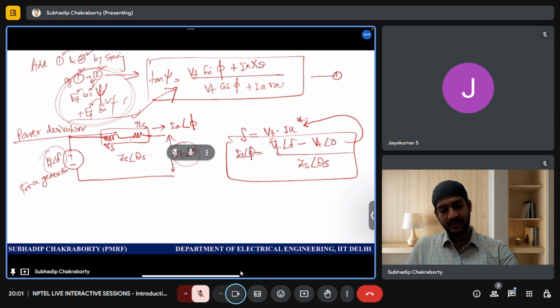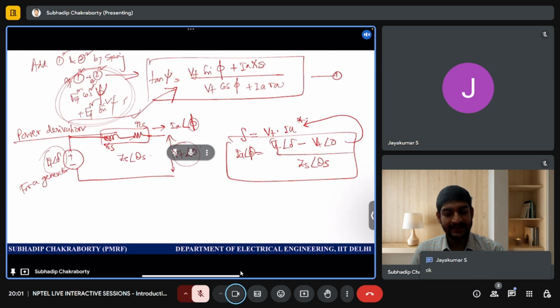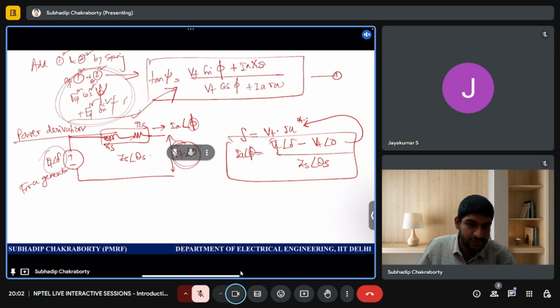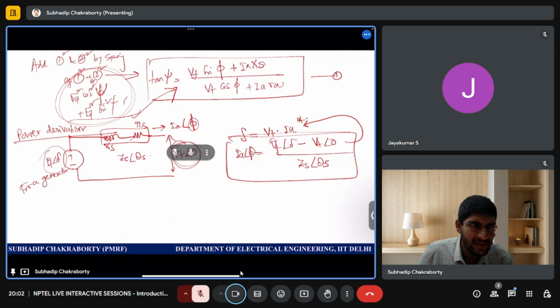This is phi, yes, because of the power factor angle, this one. The angle between VT and IA, and I took the reference of VT, right? That's why I'm telling phi. So VT has an angle 0, and with reference to VT, IA is standing at an angle of phi. So I should write phi. I need to take one reference and write all angles in reference to that angle. So as we can see, the angle between VT and IA is phi. That's why I'm writing phi. Now plus phi or minus phi, the formula will give me. I know that there is some angle phi; whether it is lagging or leading, mathematics will give me, right?